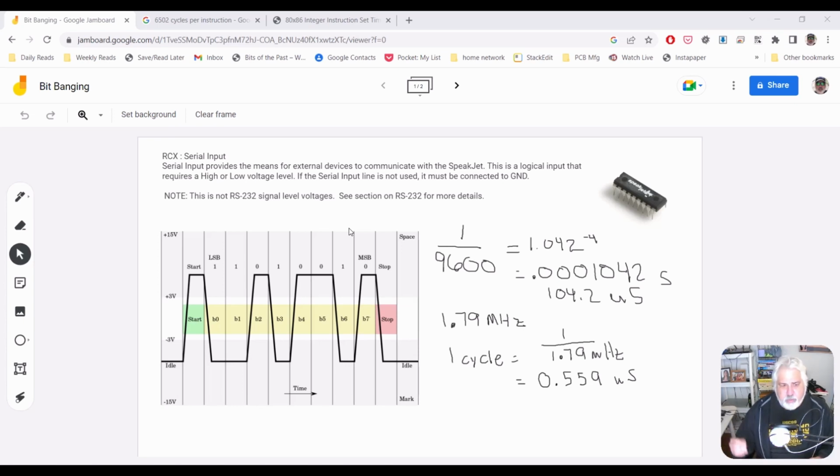If you remember, in that IDE, you choose the baud rate, and I believe it's no parity, one stop bit. What does that mean? What does 9600 baud mean, for example, and no parity, one stop bit? Well, you're going to have to know what that is because you're going to have to write it in software. So let's take a look real quick at an RS-232 data packet, a data frame.